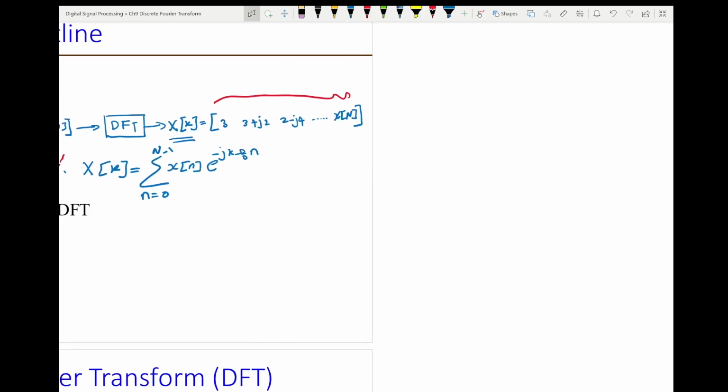So your sensors may pick up a continuous signal that looks something like this. The first step after the sensors pick up this signal is to take samples of it, if we want to process it using digital equipment. So the first step is you determine how many samples per second you need to take.